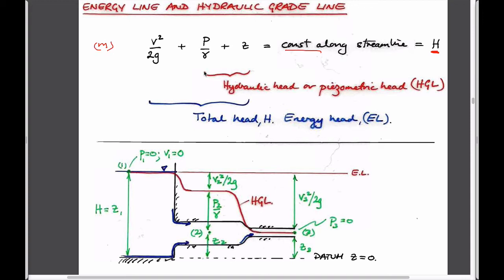The other way to think about this division is to divide it into what's often referred to as the hydraulic grade line, which hydrologists would call piezometric head. Piezometric head is the total head within the system that neglects the velocity term. It's convenient in petroleum, geothermal, and groundwater systems when you look at flow in aquifers and reservoirs, because typically the velocity squared term is tiny. It's a creeping flow, there's no destruction of momentum in the system, and we don't care about that fact.